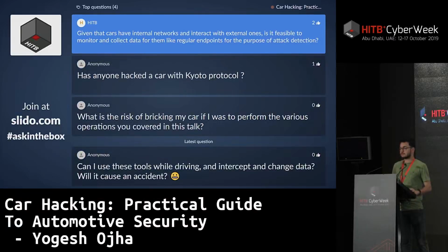What kind of fixes or countermeasures would you recommend against these attacks? One of these fixes could be using encryption, with a private key in a small hardware chip, so that once you have the encryption, it's really difficult to reverse engineer without getting the private keys. The other thing is implementing the IDS and IPS so that fake packets cannot be injected from the OBD ports. Those could be possible solutions.